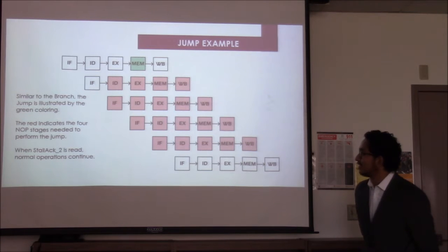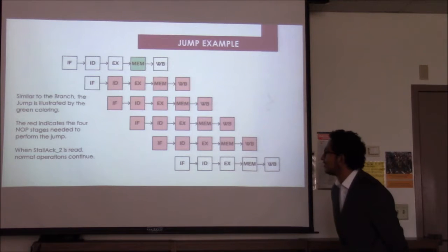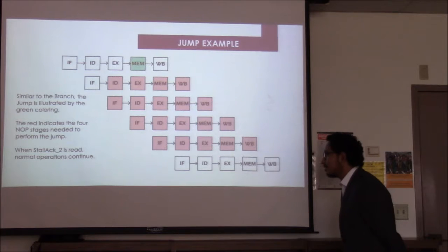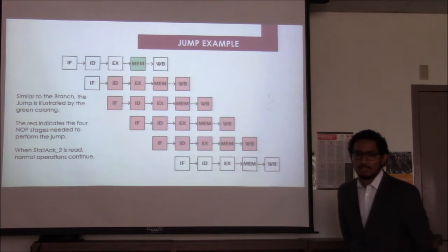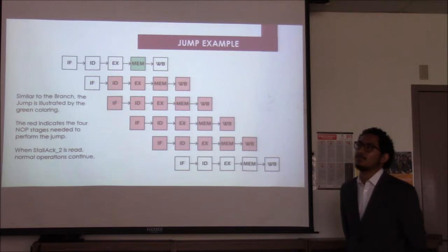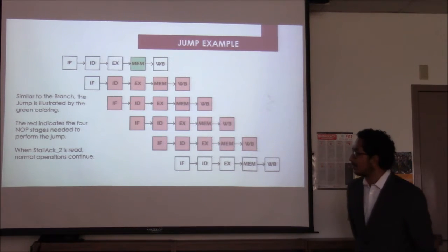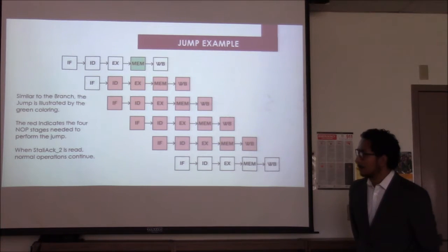Technically, we could have taken 3 stall stages, where the next instruction fetched could have been here, but we ran into problems of timing, where we figured it was because PC needed to be loaded and the instruction registers needed to be loaded, so we just added an extra stall cycle for everything to settle down. So that may have been a simulation problem versus a hardware problem. Okay. Yeah, we were having a couple of those.